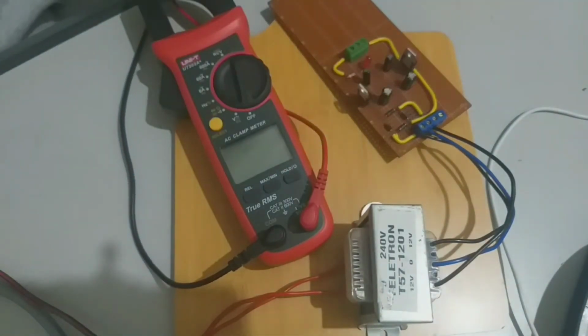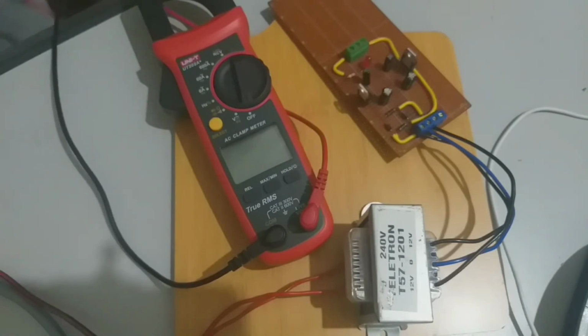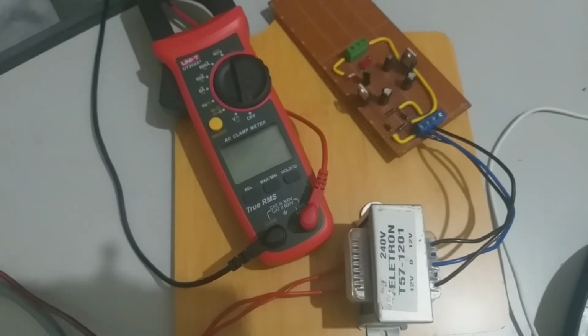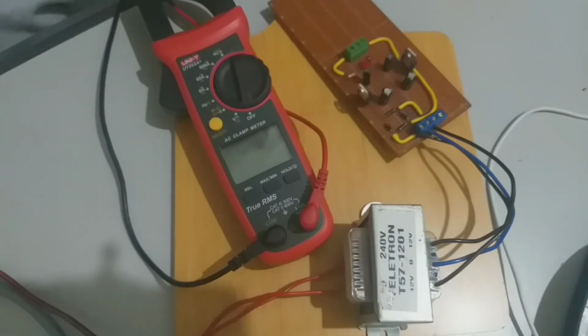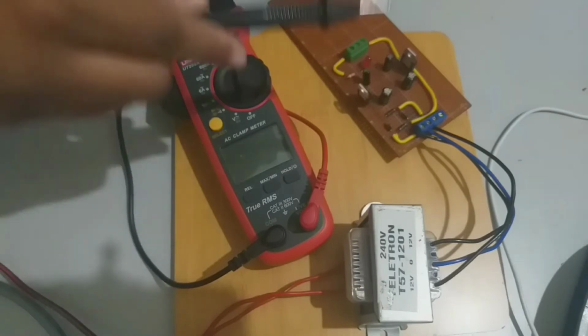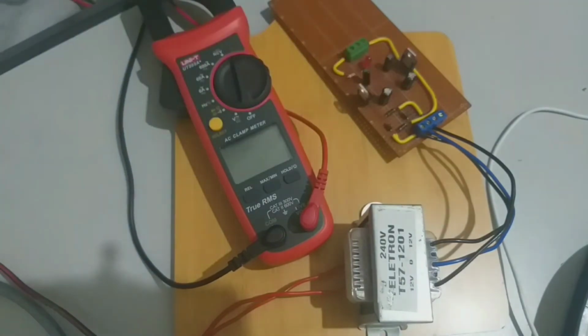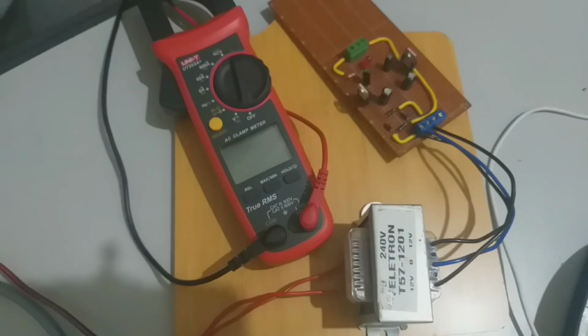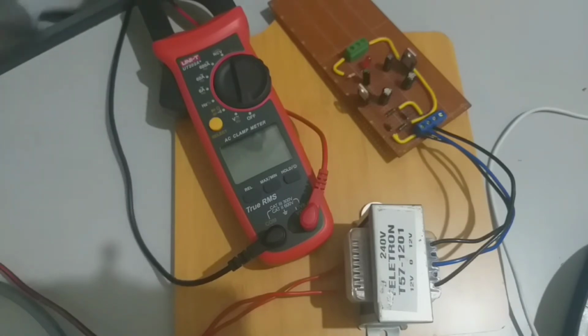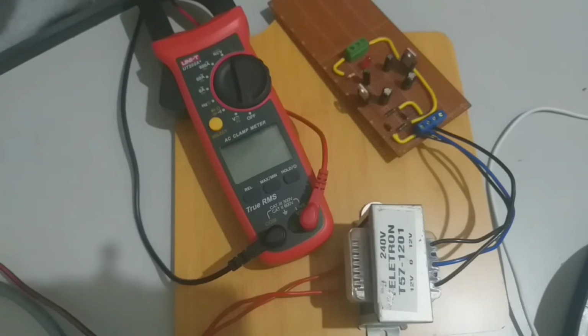The third process involved in the circuit is smoothing. To smooth the output of the rectifier, a reservoir capacitor is used. It is placed across the output of the rectifier and in parallel with the load. The smoothing works because the capacitor charges up when the voltage from the rectifier rises above that of the capacitor, and then as the rectifier voltage falls, the capacitor provides the required current from its stored charge.